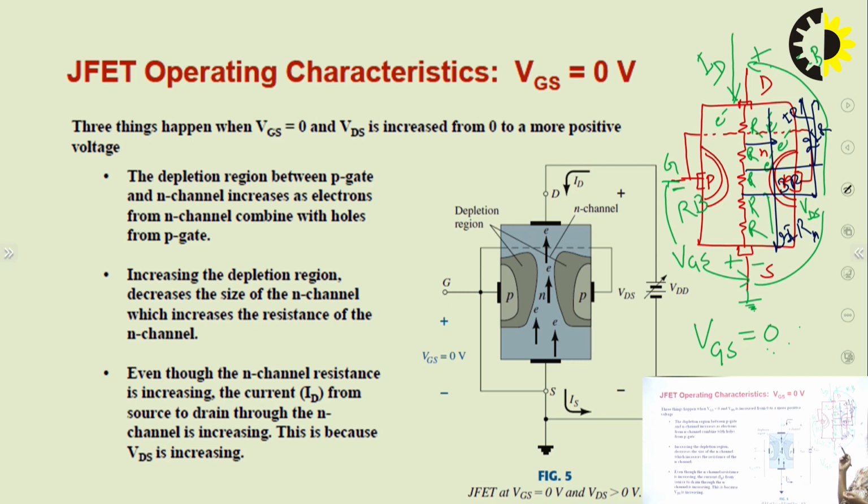And also we know that this voltage is a reverse voltage, because drain to source terminal is reverse biased. When we reverse bias a PN junction diode, the depletion width starts increasing. And because the drop across the last resistance is more than across the first resistance, this depletion width thickness is also not uniform.